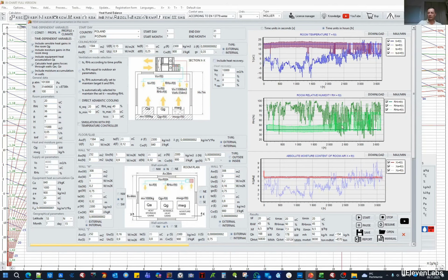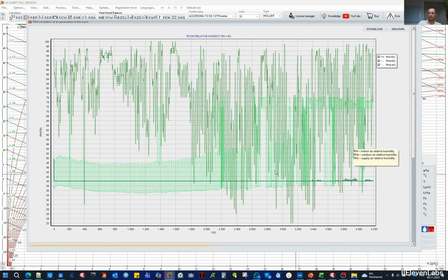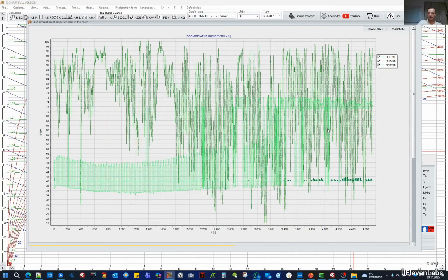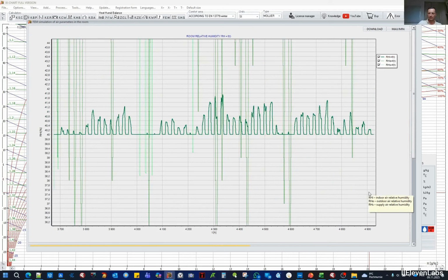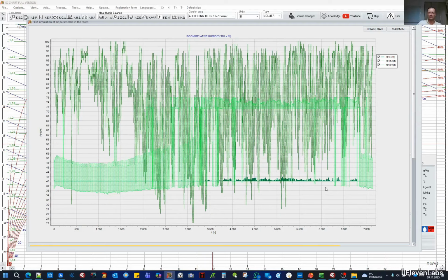Well, here we can already see that certain signs are appearing, indicating that this humidity cannot be maintained all the time, that there is already a bit of a lack of system efficiency, and here we can see some kind of jaggedness in this graph. Which in other words means that a temperature of plus 5 degrees as the temperature of the cooler wall or the supply air, limited to plus 10 degrees, does not allow us to achieve the required relative humidity.